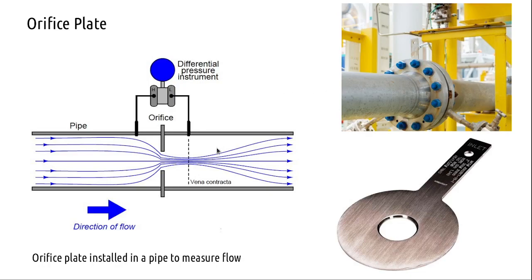So this is a much more detailed description of the Orifice plate. Your pressure head P1 is on this side and P2 on the other, and the direction of flow is along this direction from left to right, and you have put a differential pressure measurement device. We mentioned gauge pressure, absolute pressure, differential pressure. So this is a differential pressure measurement device.